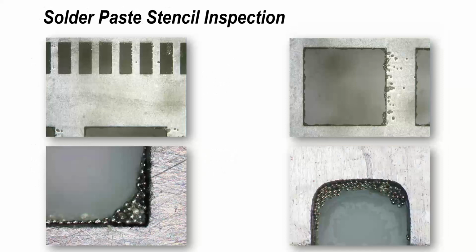So what we should achieve is stencils that are absolutely perfectly clean, not like the examples I show here. So if you look at this example, you can see that we've got quite tight apertures. Some are on QFN, some on through hole, and some finer pitch on the bottom here. And again, you can see material hanging up.